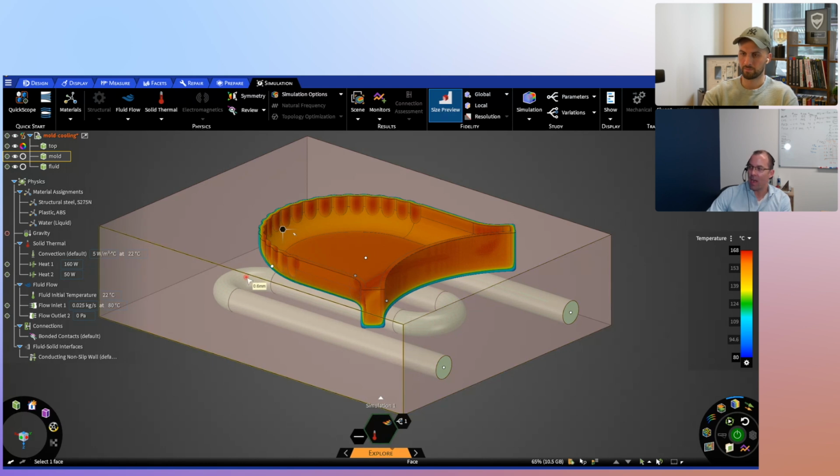What do we care about? What's the average temperature in here? Throw 2 thermocouples on. What's the outlet temperature here? Throw a thermocouple on. What's the flow rate? When I go to match the test data, I'm only putting 2 or 3 sensors on here, the most important ones. So forced convection, conjugate heat transfer without radiation, all good.